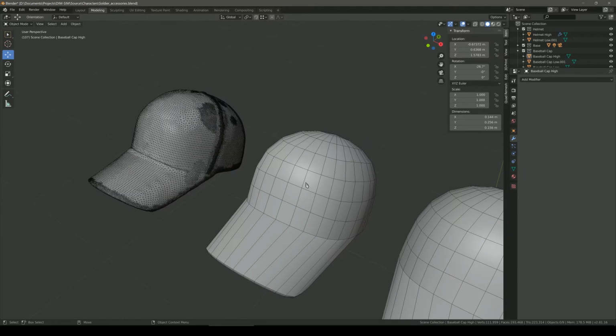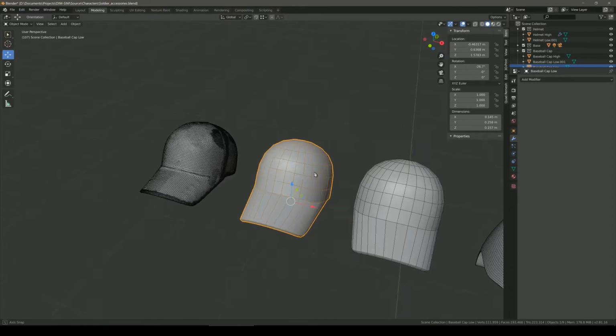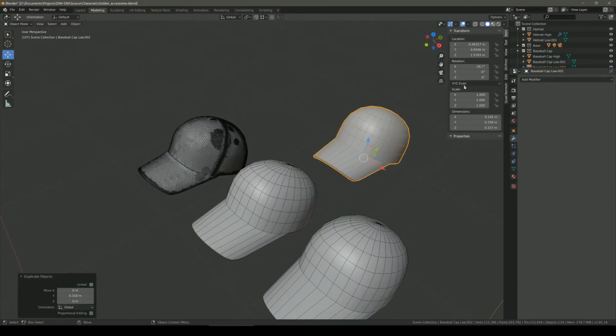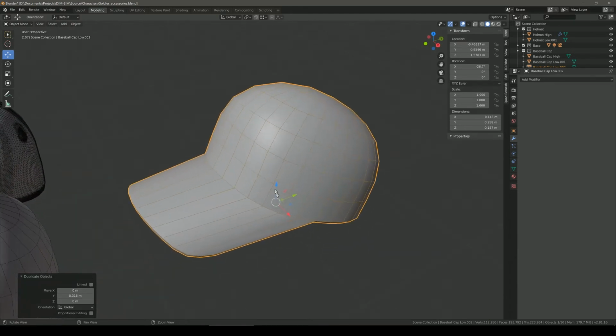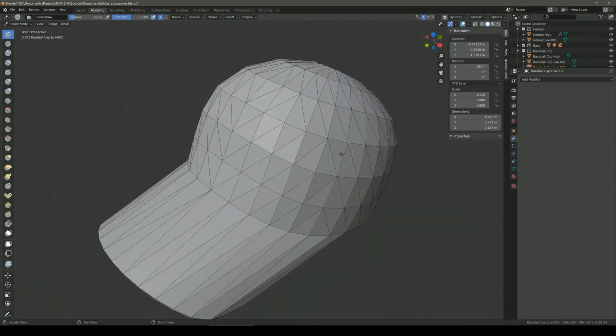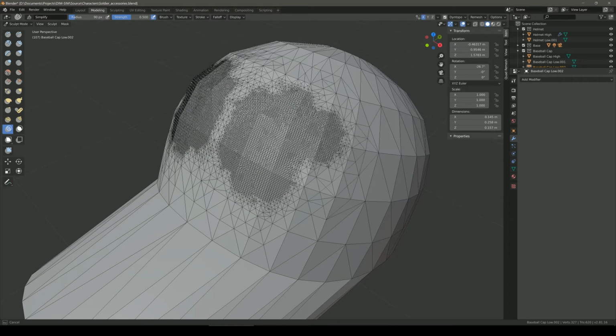And there's a few ways to do this, but probably the easiest way is to start with the low polygon. So you might build a low polygon prop like this. That'll be a typical starting point. Duplicate it, move it over, and then start sculpting on it to make a high polygon one. So if I go to sculpt mode in Blender, I'll turn on dynamic topology so that it creates new polygons, and then I can add polygons like this to make it high resolution.